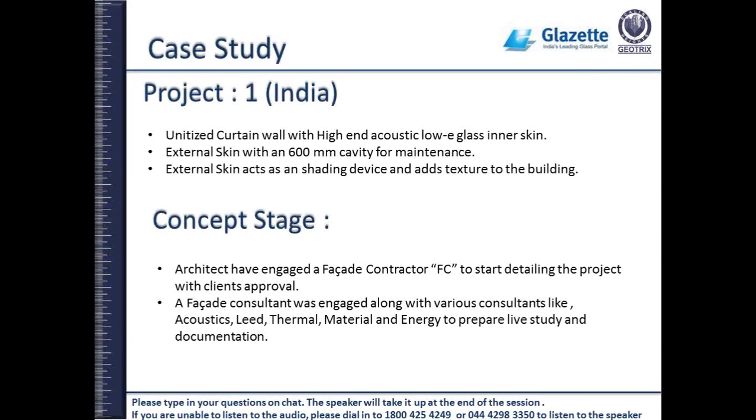See, normally when we do modeling, we take a building. When you want to do an energy model, we just mask the building, put it in software and run the sunlight analysis or daylight analysis, whatever. But most of the time we were not able to get the correct result as predicted by the software because we don't model the complete surroundings.